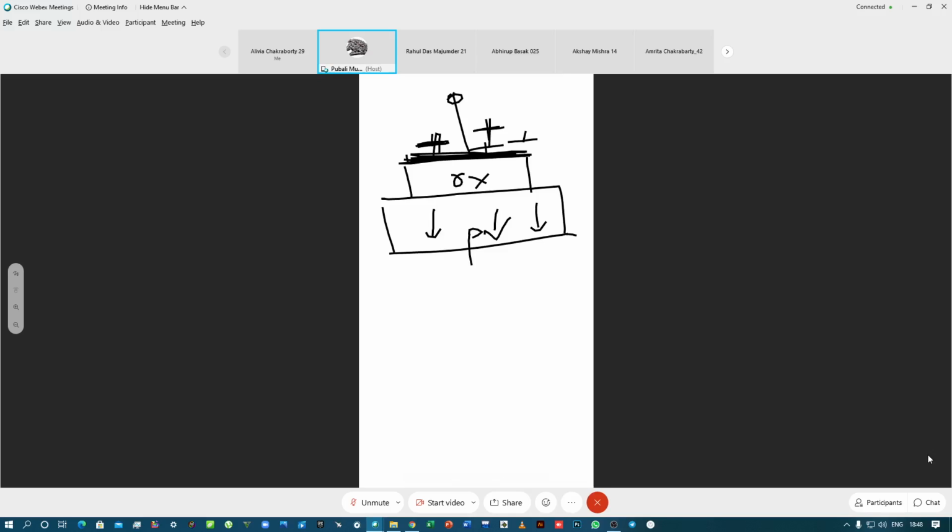It is as if there is an induced space charge region over here with negative charges, or you may also think of it the other way around, that it is pulling, as we had discussed in the case of our MOSFET. Both concepts are two ways of thinking about the same thing. That is, as if you have attracted negative minority carriers from the p substrate, and they have accumulated over there.